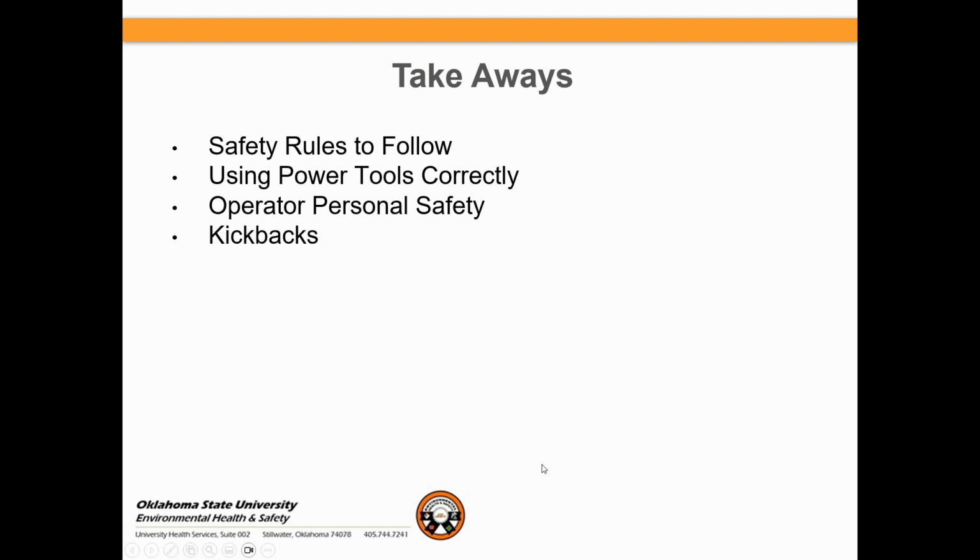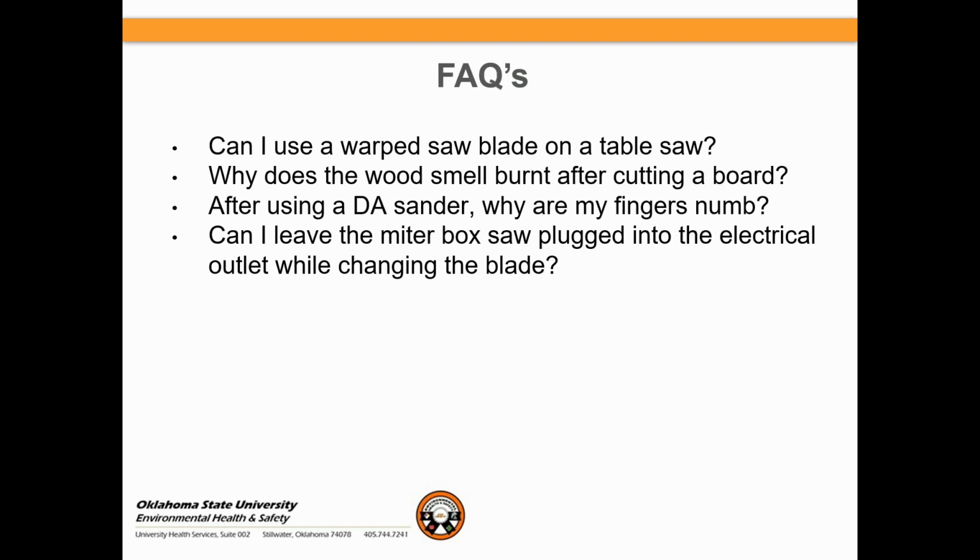We did come up with a facts and questions sheet, just a few short questions to help you out. Can I use a warped saw blade on the table saw? Well, the answer to that is no. You say, well, Greg, why not? Why can't I use a blade that I previously have? Well, a warped blade on a table saw is going to give you uneven cuts. The other thing is it may not cut off everything that's in line during that time. So those are some things to look for there.